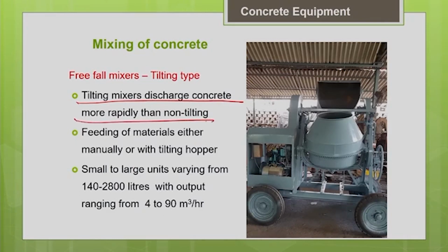Particularly for concrete, time is very critical. Once you prepare the concrete, once you add the water to the cement, the cement will start setting. That is why as early as possible we should place the concrete in the desired position. That is very important with respect to concrete. Another important thing is that it is a composite material. It is made up of different types of material like coarse aggregate, fine aggregate and cement.